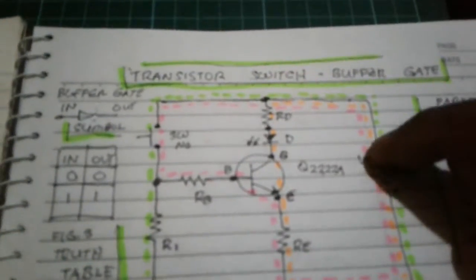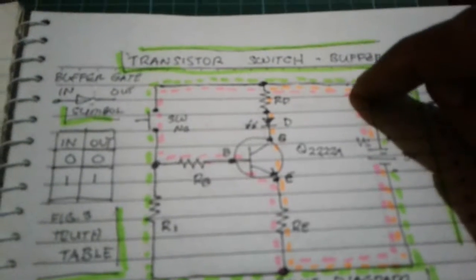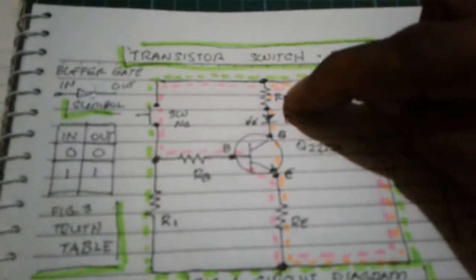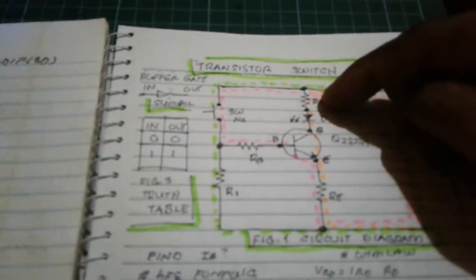And then we now find RD. So RD here, by using Kirchhoff's voltage loop, going to use this orange line: voltage supply here minus the voltage drop across the resistor, diode, transistor, and the resistor at the emitter side. So I supply here, the voltage drop, collector emitter saturation is given in the data sheet, and that is 0.3 volts.